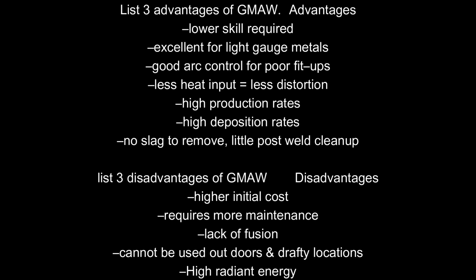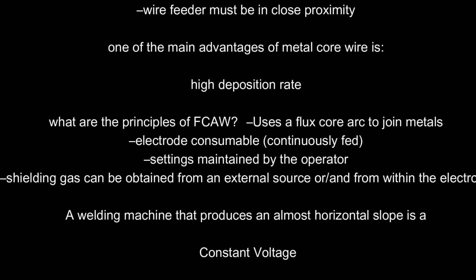List 3 disadvantages of GMAW. Disadvantages: higher initial cost, requires more maintenance, lack of fusion, cannot be used outdoors, drafty locations, high radiant energy, wire feeder must be in close proximity.